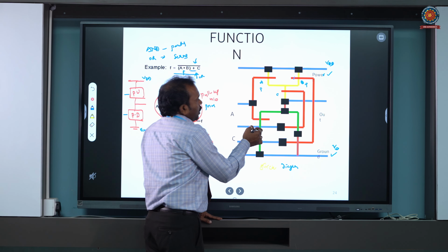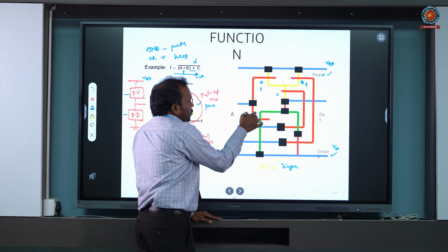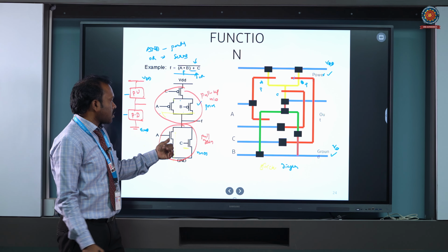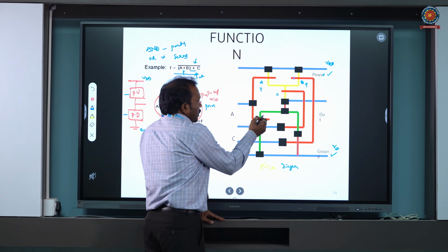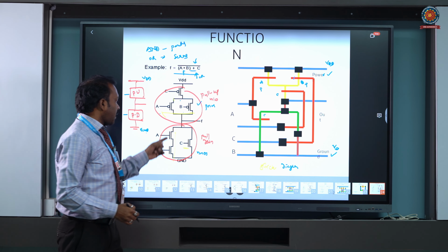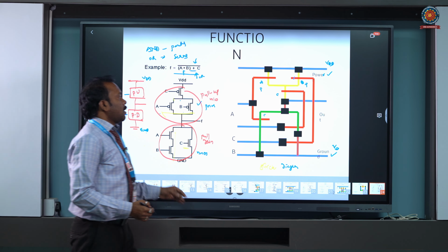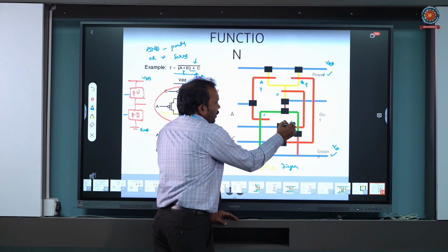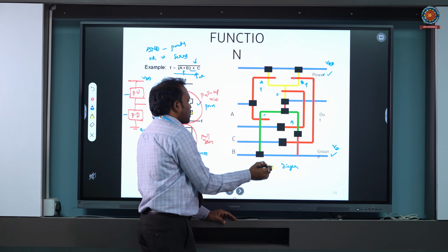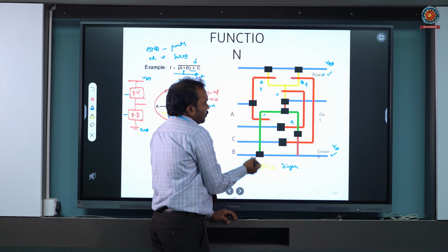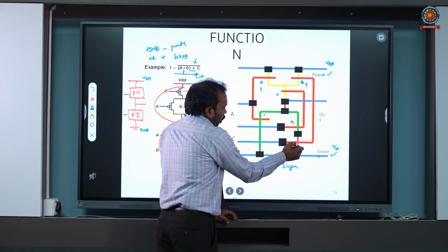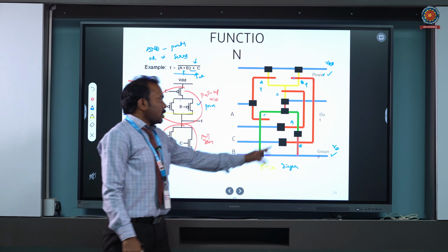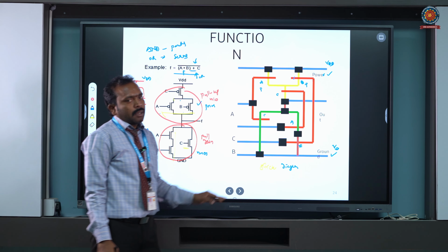And see here, this is one more where this red is formed, the red over green, this forms one transistor as you are seeing here. Let us say this is C as per the figure, and AB are connected in series. Red over green forms transistor A. And here sometimes dark brown can also be used, okay, and this forms transistor B. And to the series combination of this, C is connected in parallel.